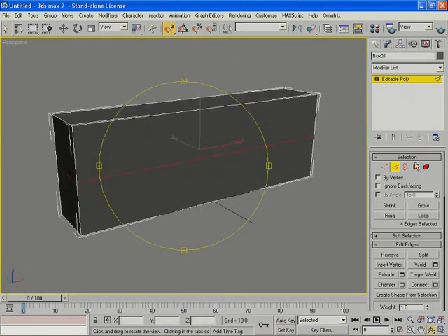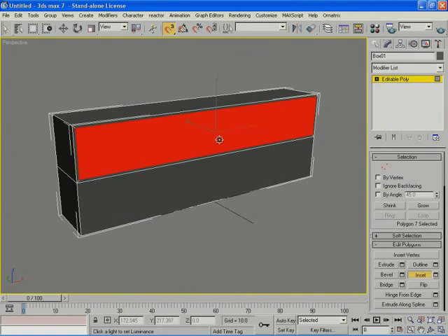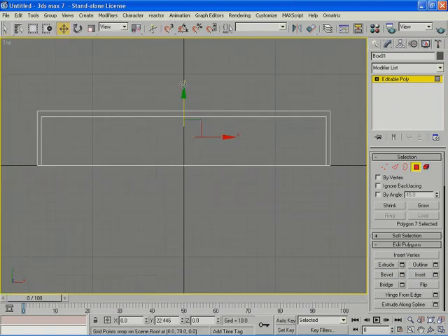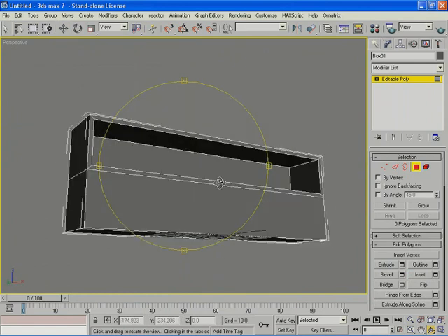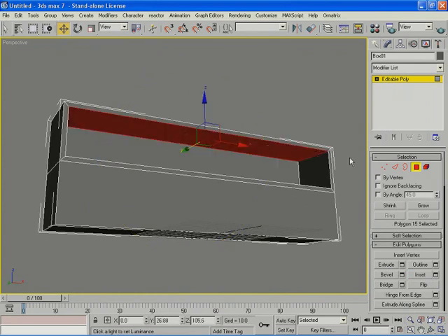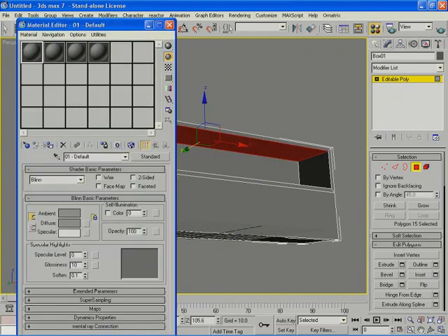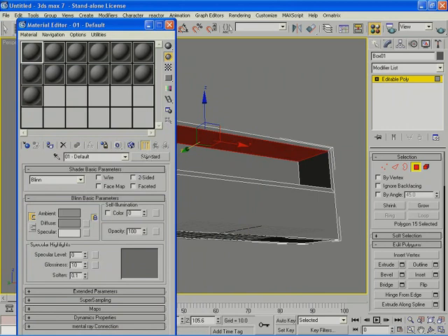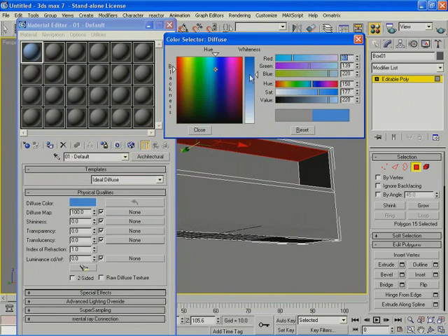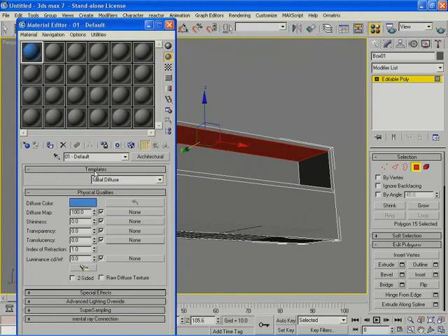Now what I need to do is give this upper polygon the light material. So I'm going to select it, press M, and for that, again, I'm going to choose an architectural material with ideal diffuse. And I'll select the color that I want this to shine with. I'll assign, and I'll increase the luminance to 5000 for now. And then I'll press Ctrl I to select the rest of the polygons, and I'll give them, for now, a regular material. Can be anything you like.